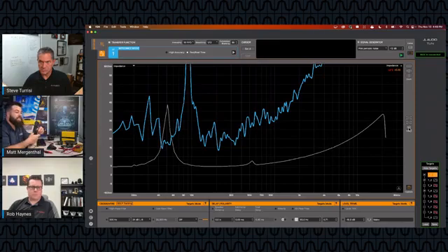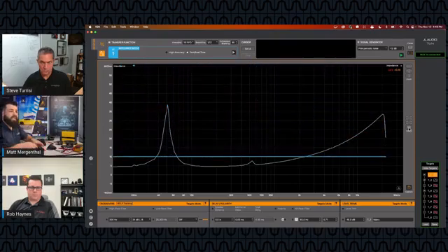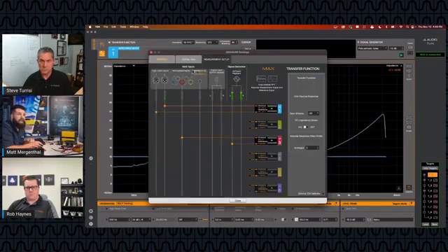So I have to actually connect the TRS probes to send the signal to the resistor. We can see that our TRS probe that's already here is calibrated. What I'm going to have to do is go back to our measure settings, and we have to route a new transfer function engine. And to do that, we need to send signal from the line level input, which is